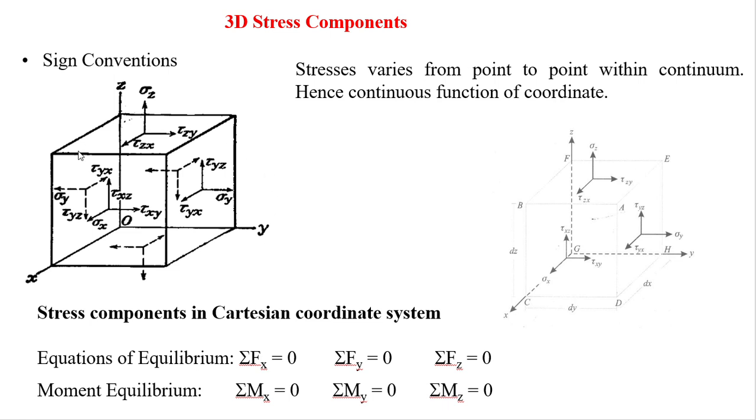To solve this, the 3D stress components are differential. To solve the differential equations, we consider three force equilibrium equations and three moment equilibrium equations. If you consider these six equilibrium equations in Cartesian coordinates, we can solve for the shear stress components, and also for the normal stress components, by using these six equilibrium equations.